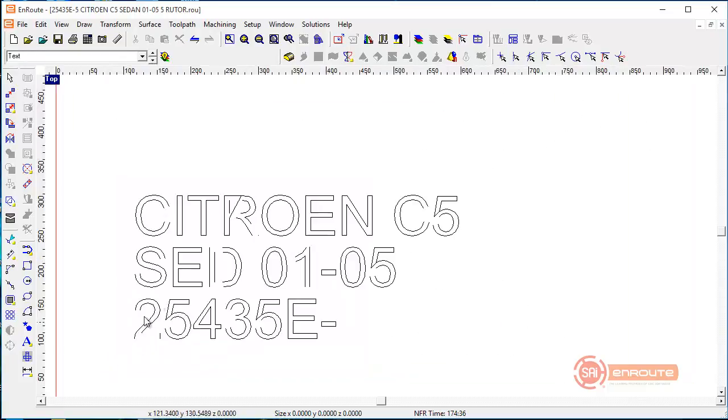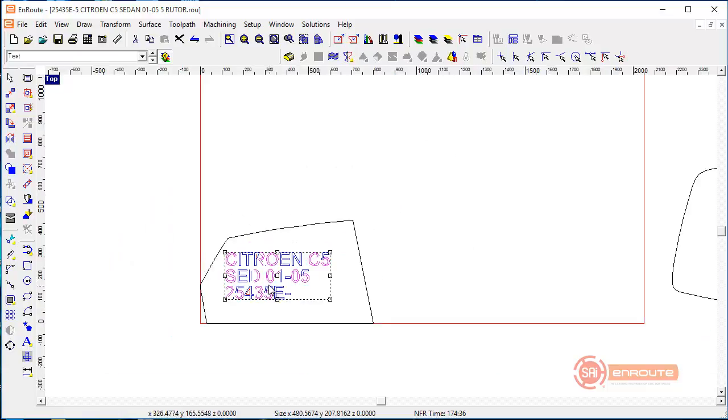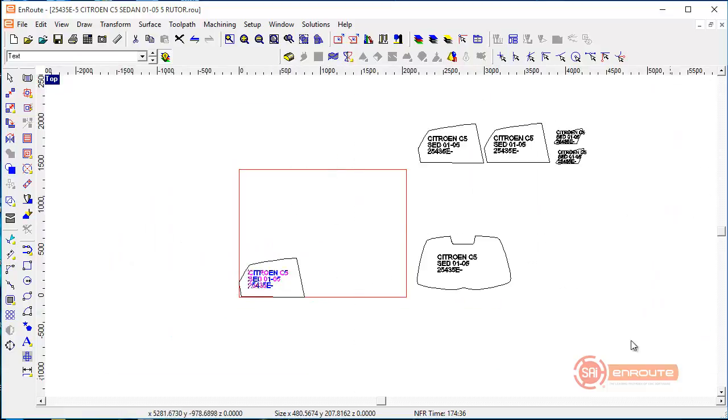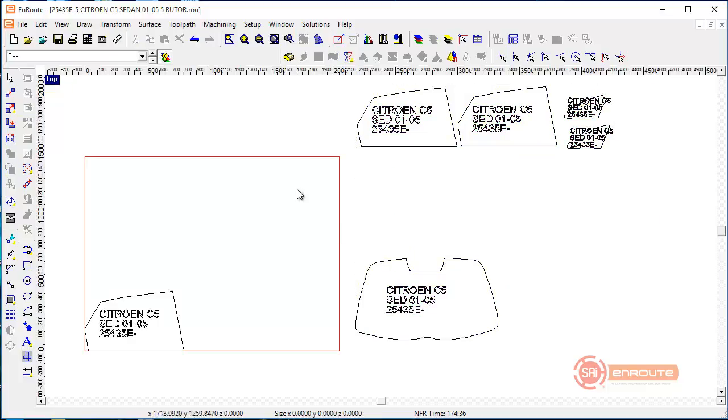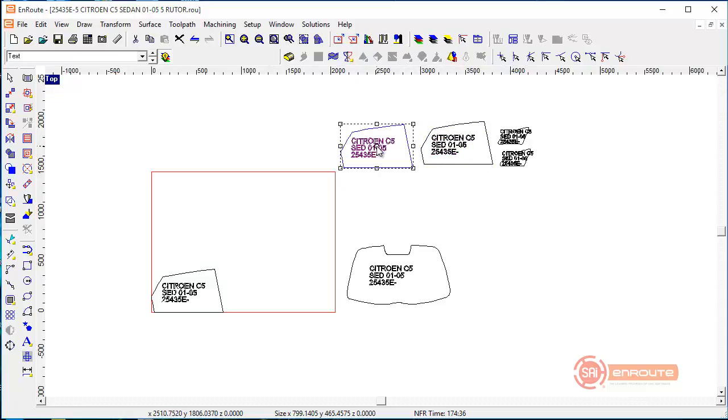Now it seems like somewhere during the export process I have a little issue to address, but when we do this, we will make sure that we have the text on one layer converted to curves and the cutouts on a separate layer. All right, so now we're going to go here and do that for each of these parts. And any place I had a duplicate, so where I had two of the exact same part, I just created a single DXF file, and we'll use a quantity of 2 when it comes time to cut the parts. All right, so that's the process here.